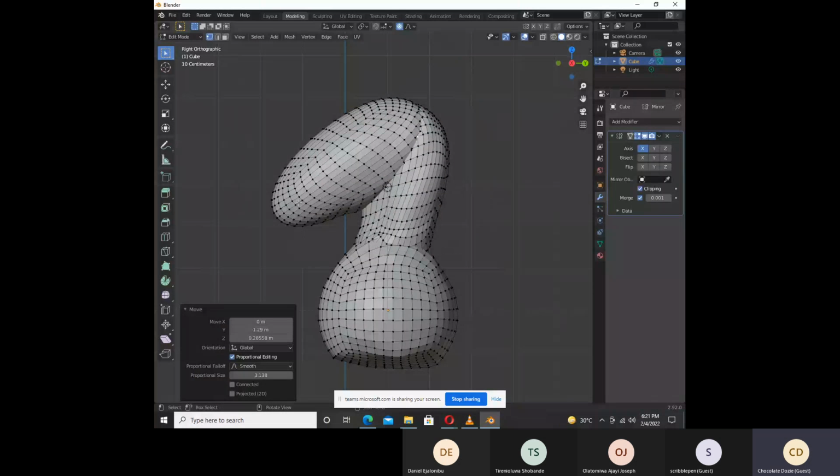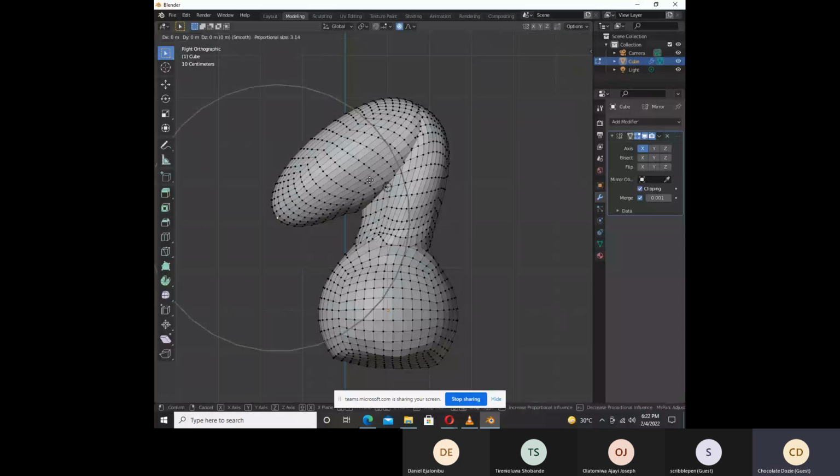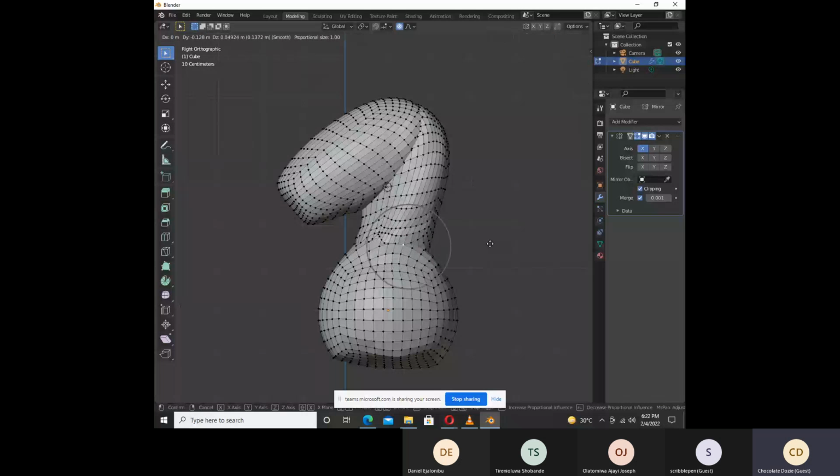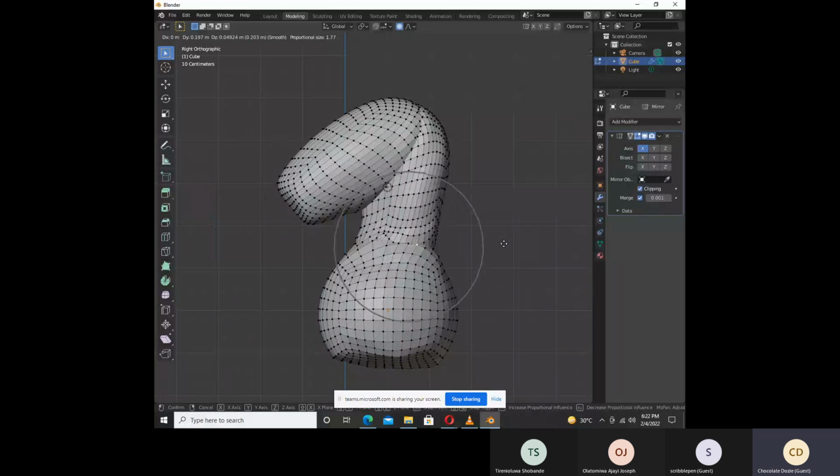Okay. You can pick another point at the tip of the mouth. Grab again, reduce your circumference this time, and then move. All right. This is in the modeling tab, okay? But this is going to get us a very good environment, or give us a good object to sculpt. That is why we're doing this, okay? So you can hold anyone down here to grab, and you enlarge, move.